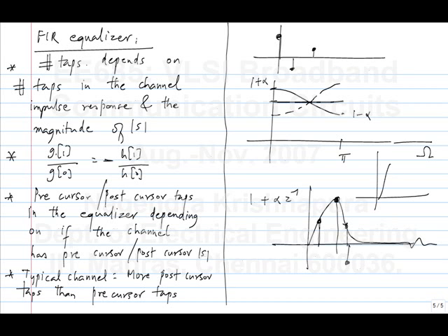That means that the output is varying like this. Okay, in one TS it is going from positive to negative. In fact, this has a high frequency boost. It's just that in practice you don't see it. You can always make up responses like this. If you have a filter whose response is like this, you will get an ISI which is negative.